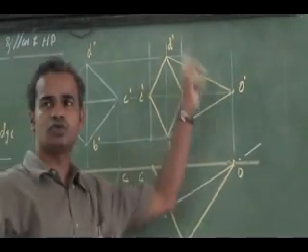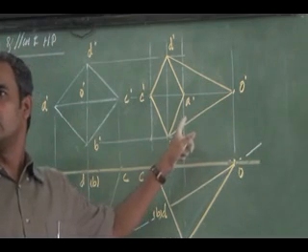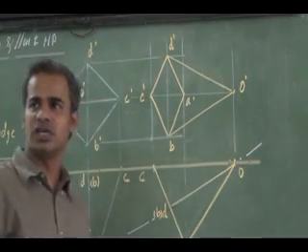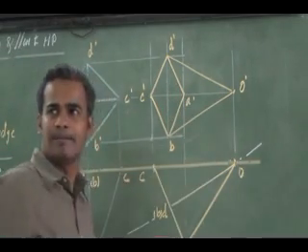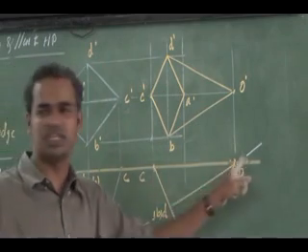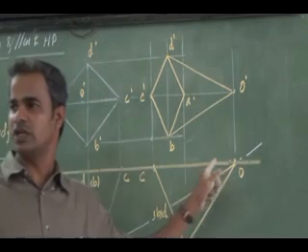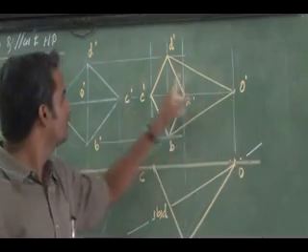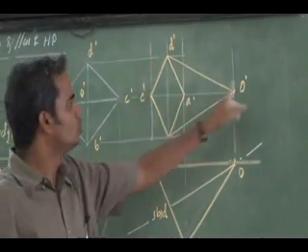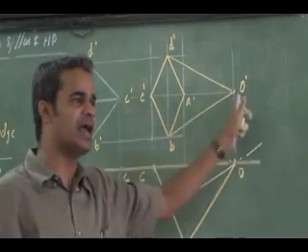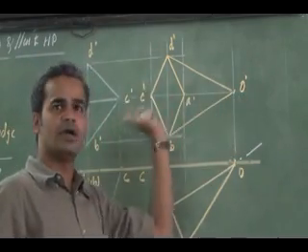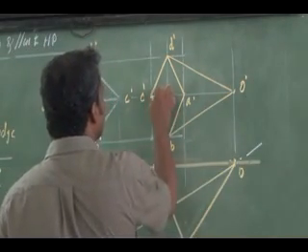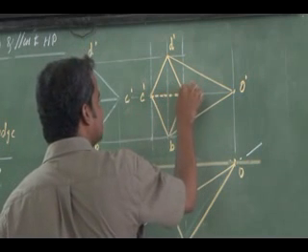Already I have got two slant edges. Then, to show the slant edges, whether visible or hidden, you have to find it out. From the top you see whichever is nearer to the reference line. That is CO, above the axis, CO is nearer to the reference line. So that CO slant edge will be a hidden one. Similarly, this is a fully visible base. If I join CO, that CO slant edge is crossing the fully visible base, so that slant edge will be dotted. So C to O will be a dotted hidden slant edge.